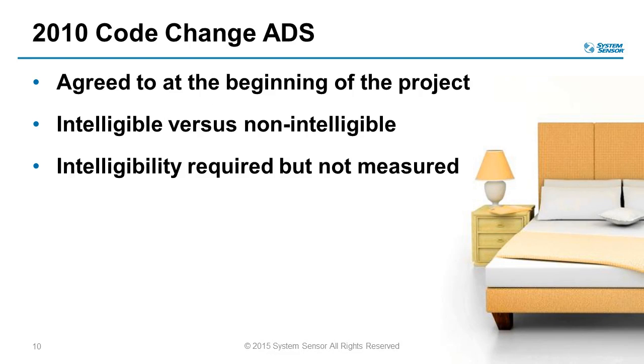Typically, the designer will segment the building or space based on physical barriers such as walls or doors. There may also be changes in materials used on the wall or the ceiling or floors, or changes in expected ambient sound levels for that space. Once these designations are made, the designer will then decide if each specific ADS should and will require intelligibility in that space. Same factors that drove ADS designation will come into play here.